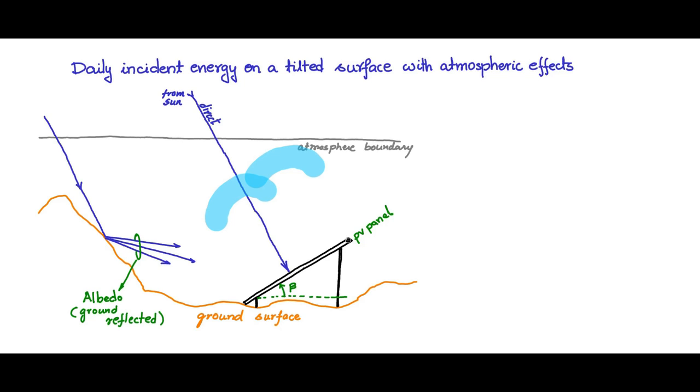You will see that there is cloud cover, and the insolation that is directed towards the flat plate collector will get scattered and diffused due to the cloud, and you will see that there will be many insolation vectors pointing in different directions, and many of them pointing towards the collector in this fashion, and this is called the diffused radiation.